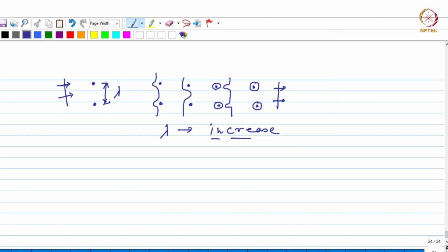Now what I said before is, for the dislocation to bend around and bypass the particles, it has to make a curvature. So it has to bend with a particular curvature, and the stress required to bend the dislocation is given by this.